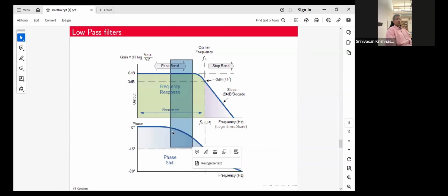The signal will begin to spread out in time. If I'm playing something on the violin, you'll see that the sound is kind of getting smeared, spread slightly out in time. So if I'm trying to play the violin very fast, you will start seeing the corresponding effect. Suppose my speaker is tuned in this particular region, you will see that the frequency amplitudes are all right. But if I'm trying to play very fast, before my re ends, when my G starts, the speaker is still giving the sound of the re. Therefore you will have the re and G kind of merging into each other, and you will have slight distortion of sound. So that's what would happen in this region.